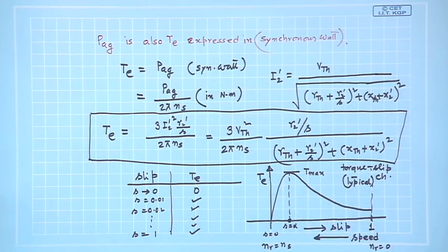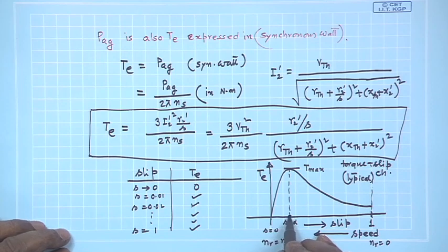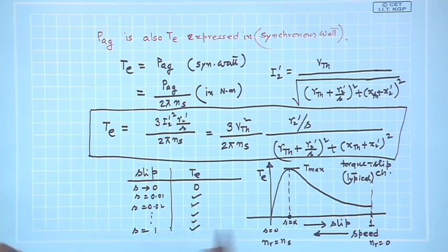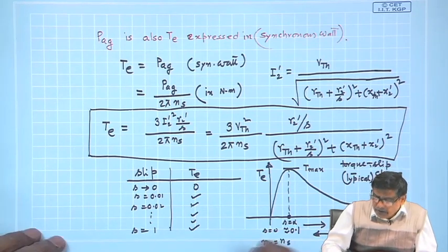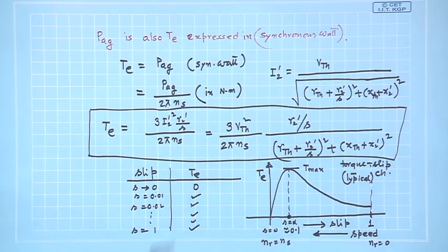For a well designed induction motor, the value of the slip at which the machine is capable of developing maximum torque will be about 1/10 of the range from 0 to 1. It is no fixed number, but the expected value of alpha will be about 0.1.